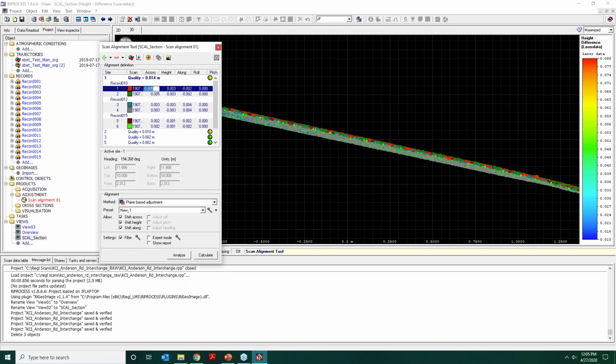So this is where we want to come in here and make sure we hold this to 0. Yes, it's going to say manually edited, but we do not want these changes, even though they're millimeter level changes, to propagate outside of our area, outside of this bridge. So we set all these to 0. And like I said, scanner 1 and scanner 2 are connected. It's not a single scan connection, it's all connected. So that fixes that, and we're good.